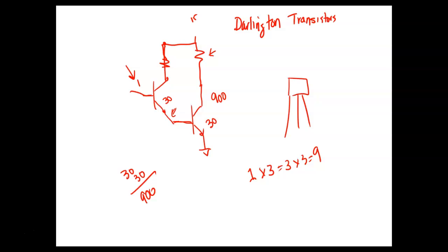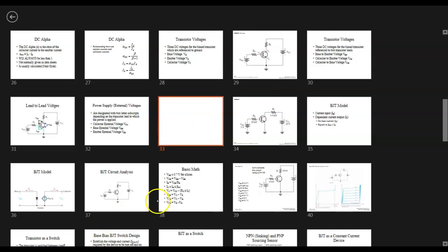So that would be 100 times 100, right? You understand that? So 100 betas are pretty interesting. 10,000. And then it's got some other features too. So this is called a Darlington pair. We can look them up, but it'll look just like a transistor, because all we need is these leads right here coming out, right? So I got this drawn wrong. Normally it's like this. Oops, sorry.